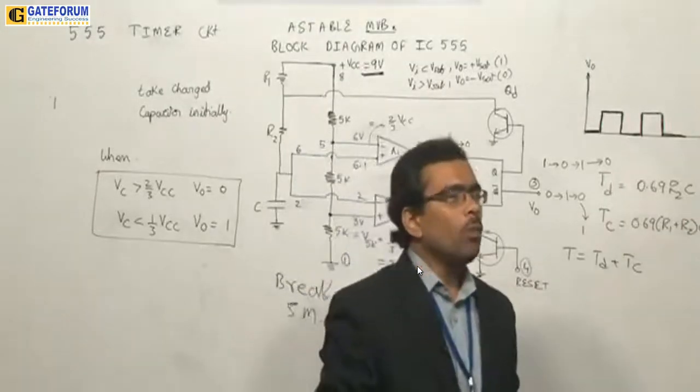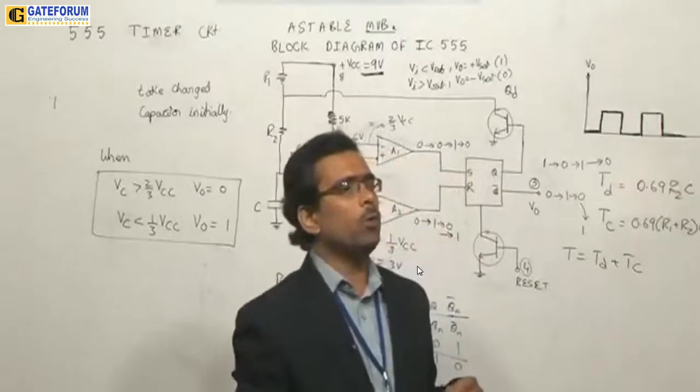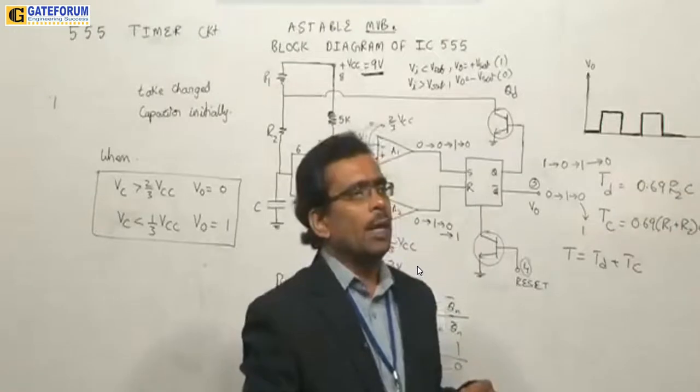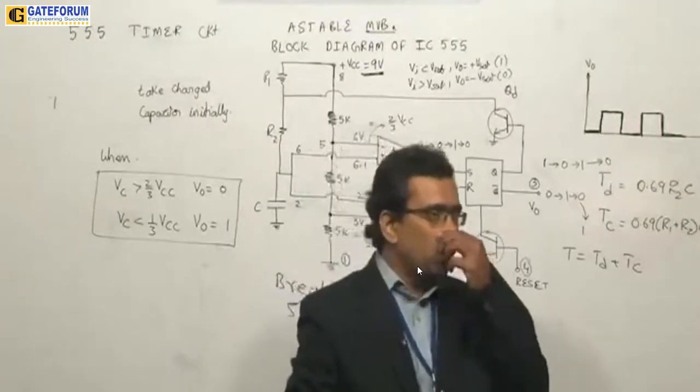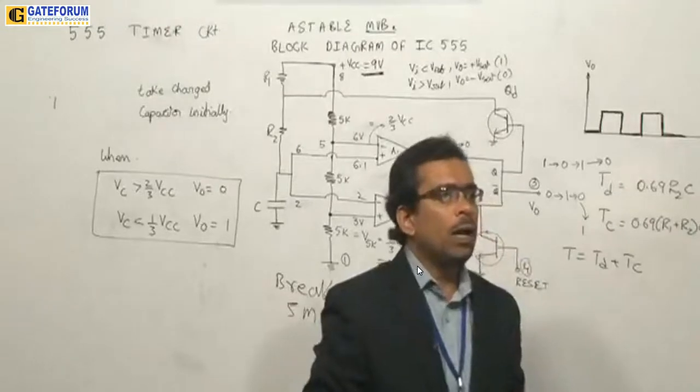Next, Ashutosh from Bhilai. Sir, as per the diagram you gave for monostable 741 structure, at the non-inverting input where diode D2 was connected, I connected a small value capacitor before the diode and in series with it. Now I trigger it.